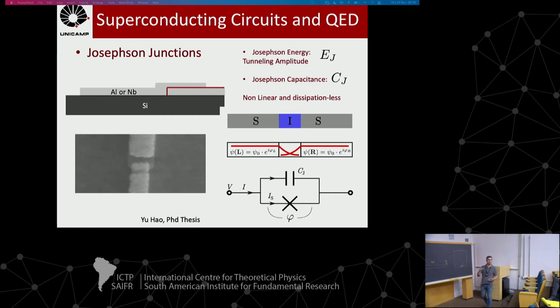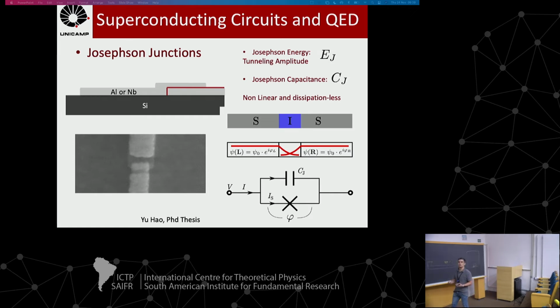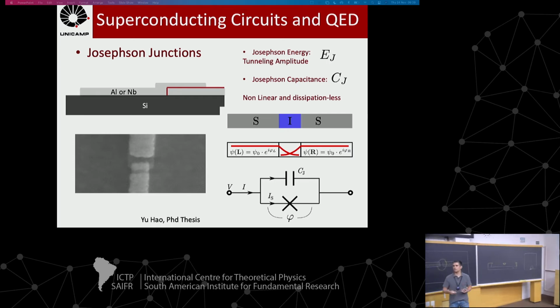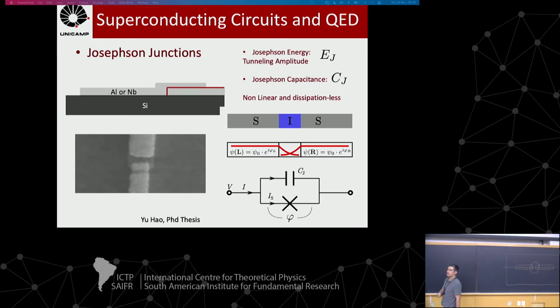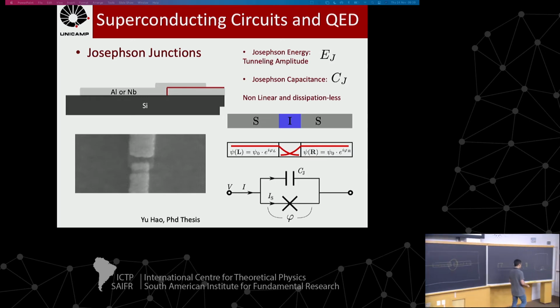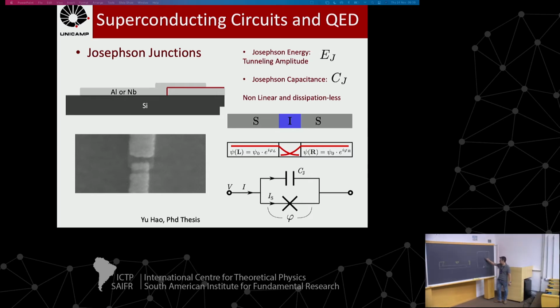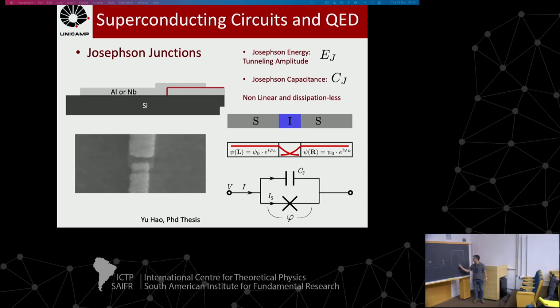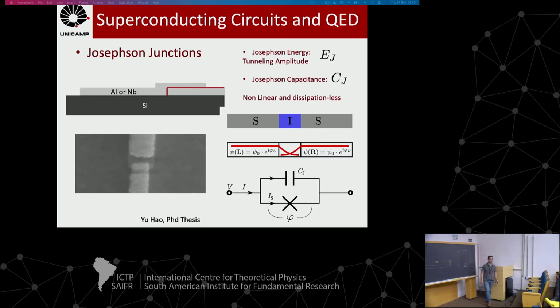When you have current passing through a material, it starts to heat this metal. When you heat the metal, it passes from the solid state to the liquid state, and then we have a liquid in vacuum. You don't have any gas inside. The atoms of aluminum start to fly away, so you have aluminum evaporating from your source.